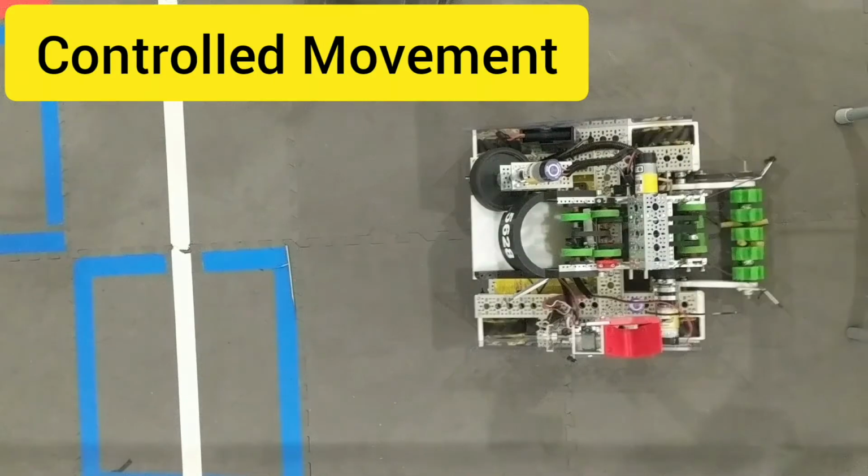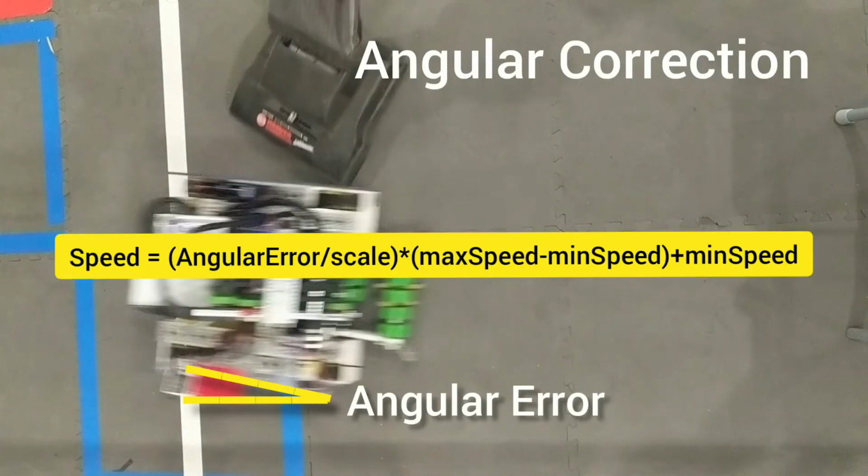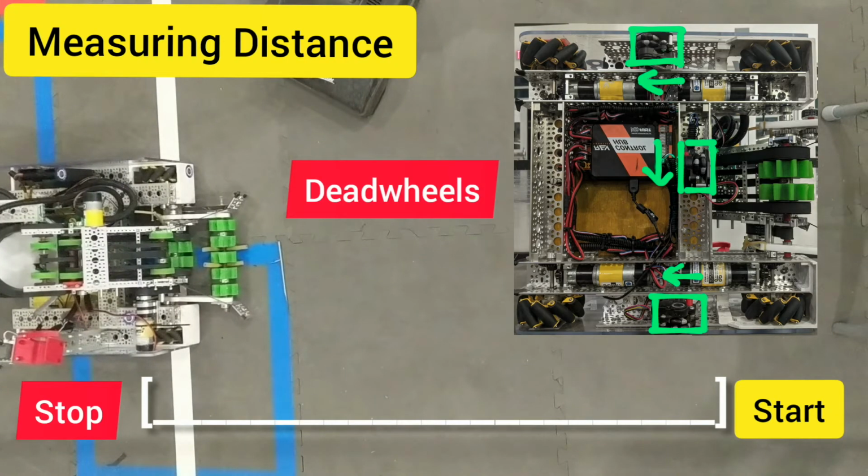For our path planner to be successful, we needed to make sure a robot executed commands to move exact distances. To not overshoot while moving at high speeds, we created an acceleration and deceleration function, which uses the free spinning wheels to calculate the error to a desired position and outputs power to feed the motors. We also correct for angle using a function that proportionally applies power based on an angular error. To calculate distance, we used free spinning wheels which return rotations that we then convert to inches.